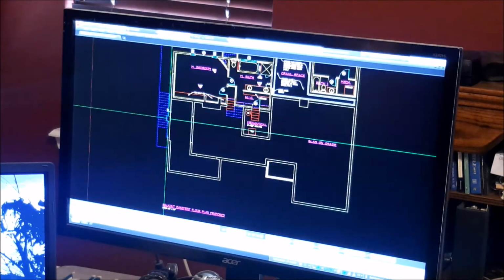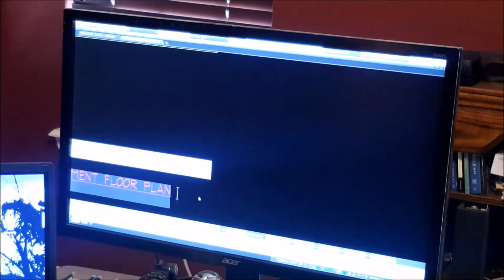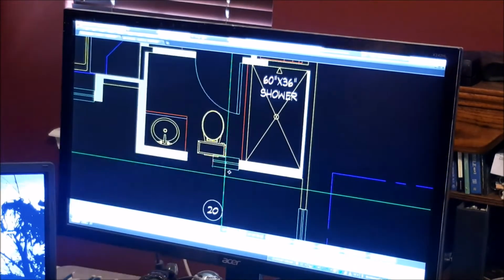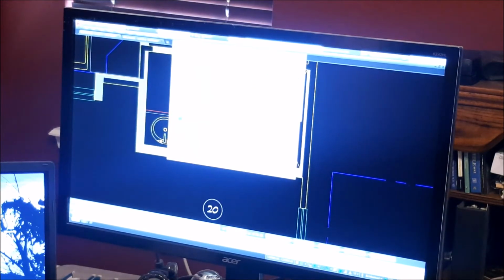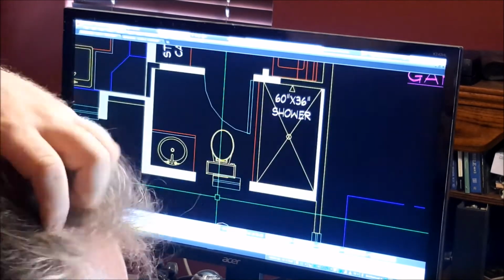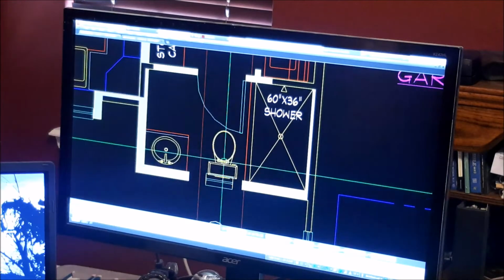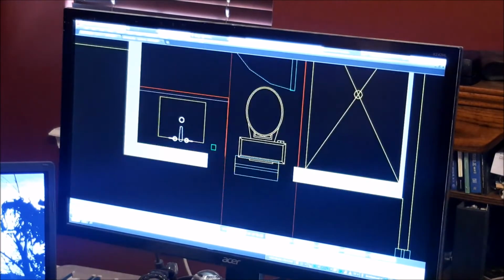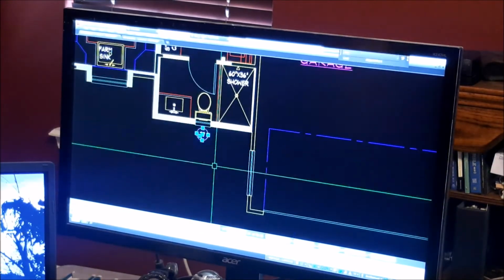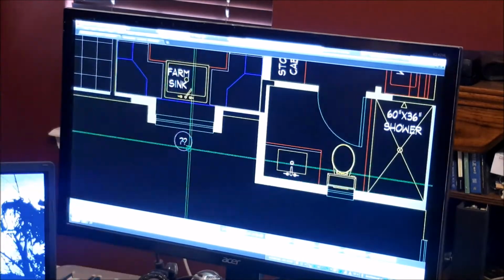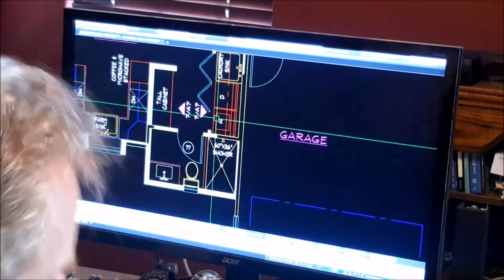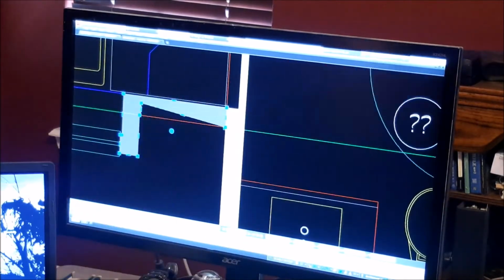What else? So I'm just updating the title blocks for him. Let's see over here. Didn't want that little wing wall. This window changed to a smaller size. He wanted to center the window, the door, and the toilet all on there. And I was also looking to see if I had a toilet that was shaped like the one he drew, but I didn't, so I just went with mine, which I got from another architect. He wanted a square sink, so I just exploded that block and used the faucet and the drain from it and showed the square coming in. I forgot to actually put that together as a block and put everything on a layer that I could send to the plumbing and fixtures layer, but I did get back to it later on.